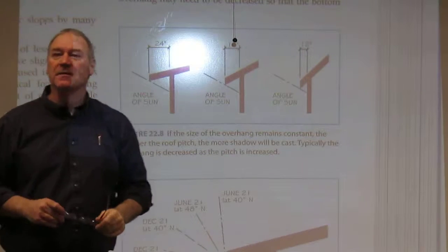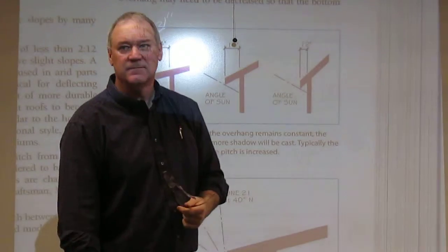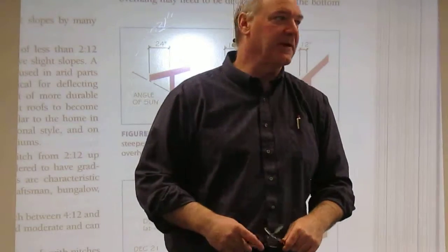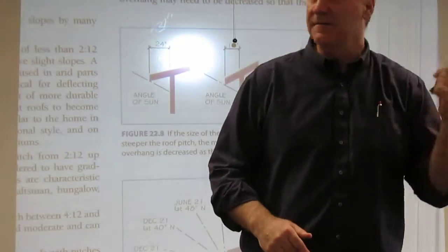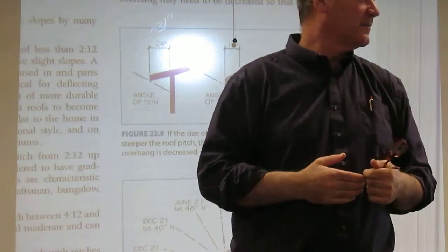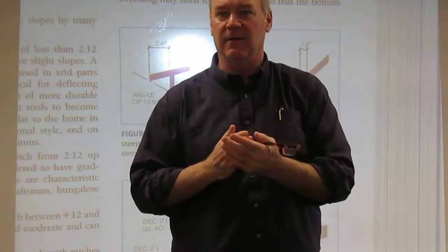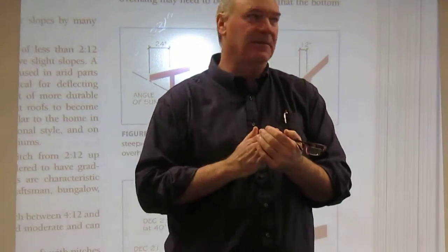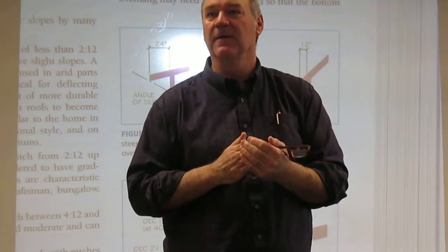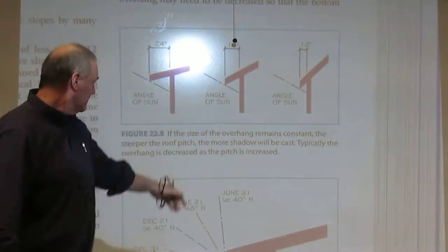Sun affects our windows on that. This is really a passive solar analysis, or what we call a sun study. And the eaves are one of the biggest things we can do to affect the performance of our house just by the design of it and make it work well. It can keep it cooler in the summer, it can keep it warmer in the winter if you do your eaves correctly. They come through a whole system here.